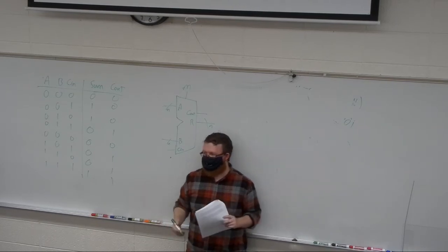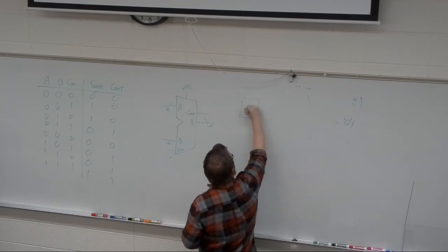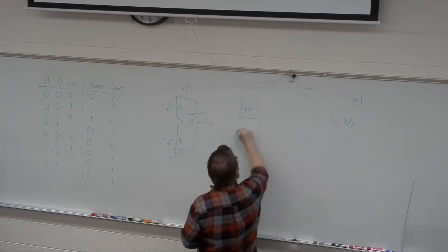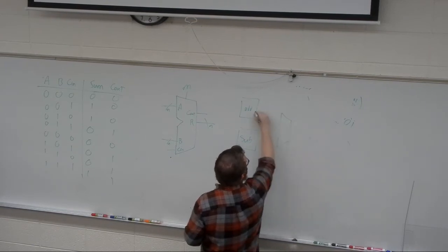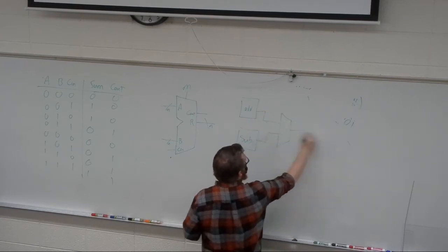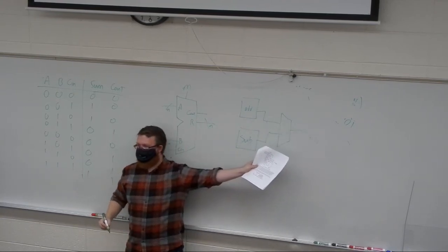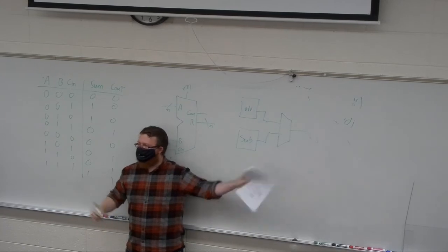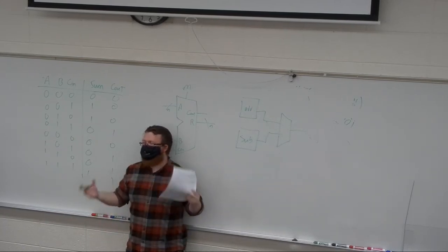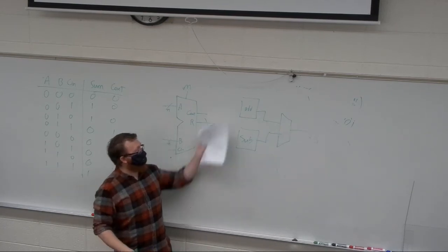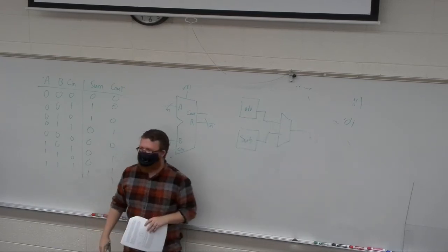A multiplexer, right? So I can just build this up as inside and say, I have an adder, I have a subtractor, and I have a multiplexer, and I get to choose which of those outputs that I have. So to build an ALU in the bluntest way possible is to just build an adder, build a subtractor, build everything that you need, and then have a muxed output.